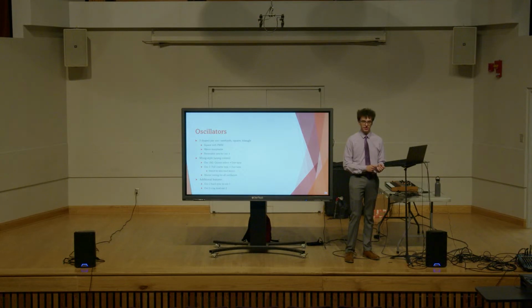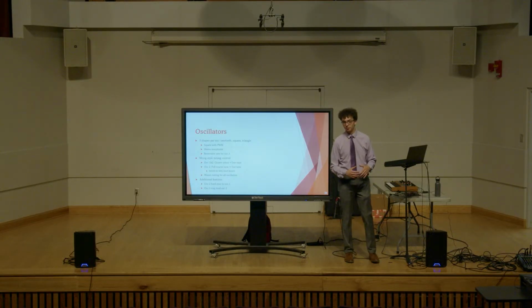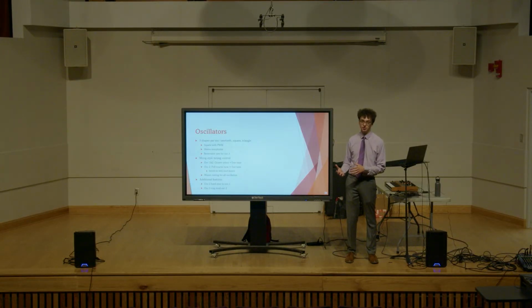Additional circuitry that I have implemented and or I'm working on implementing is a ring modulator between oscillators 2 and 3, which is a whole separate output and will be a separate input in the mixer, which I'll show you later. And then hard sync for oscillator 2 to oscillator 1, which causes oscillator 2 to reset every time oscillator 1 does. And that can create some really interesting harmonic relationships between the two that I'll play in an audio sample for you.